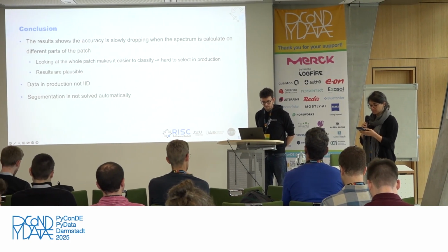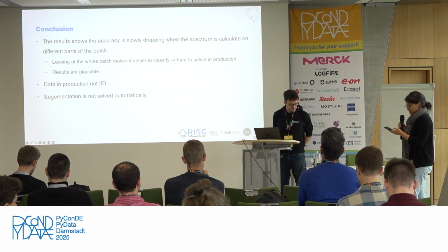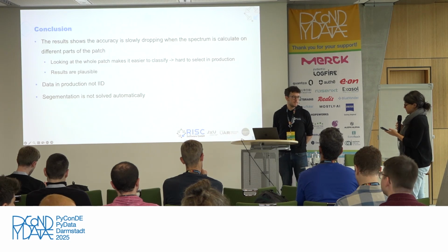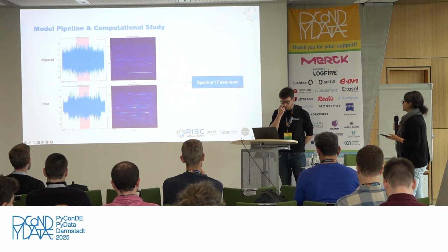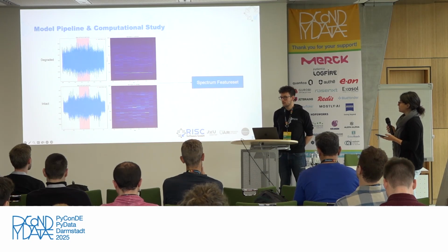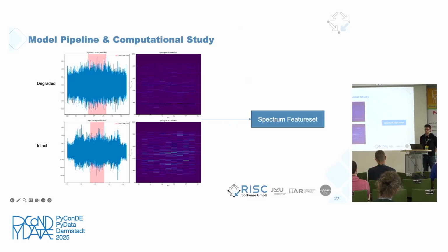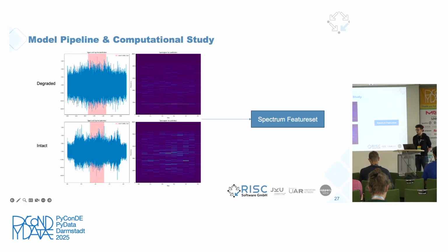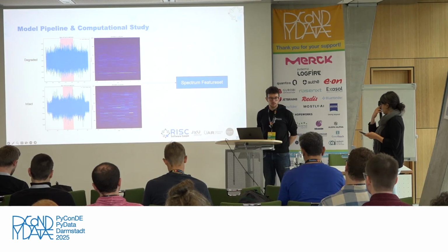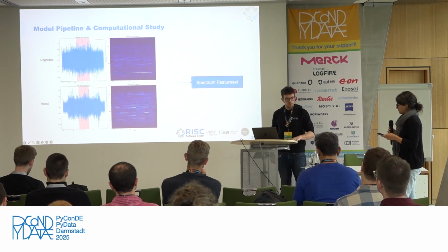The first one is, I would say, 2 in 1. Could you describe the sensor in more detail, and also what kind of sensors or microphones did you use, and what parameters did they measure? The sensors are structure-borne sound sensors, which is a standard sensor in industry. Imagine a microphone. Normally, you have sound waves you measure with a microphone, like the one near my mouth right now. If you don't measure sound waves in the air but in a body, it's suddenly a structure-borne sensor.